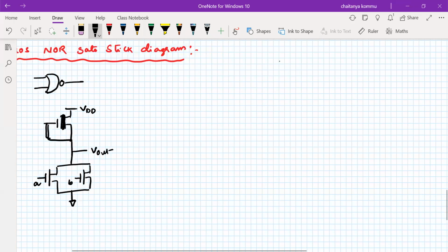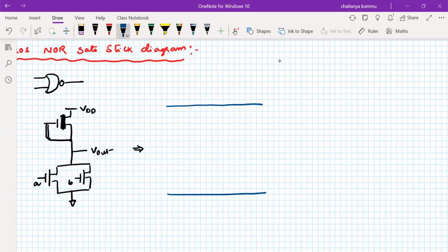Now what I can do here is simple, just within 2 minutes I can write it. First, I have to take the power lines, VDD and ground. The second point is the diffusion lines I have to draw. One diffusion here, another diffusion here, another diffusion here, right? Then I have to cross a polysilicon over there so that it will be acting as a transistor. Therefore, the three transistors I have shown. Now provide the connections between these. Since these are all the same materials, NMOS transistors, that's the reason why I'm extending the diffusion.